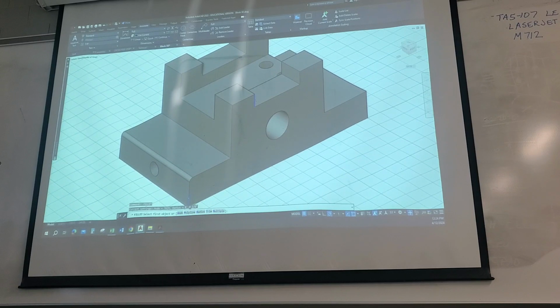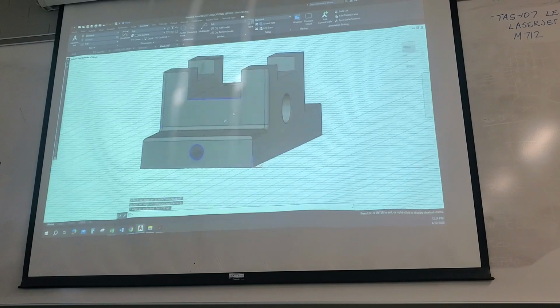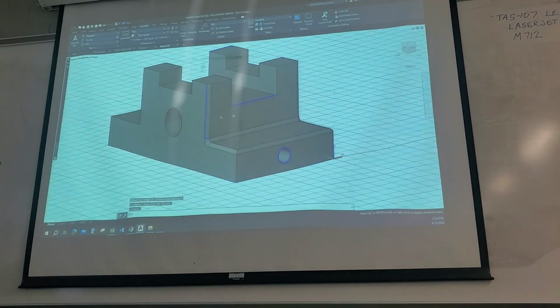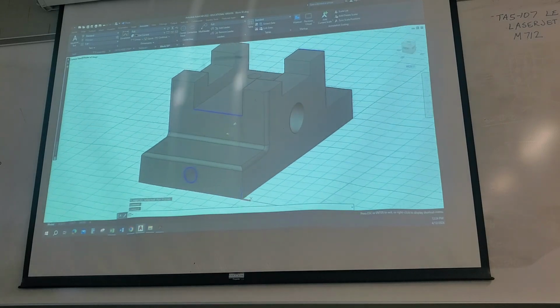On a 3D object, I can go back into it. Once again, I can pick that edge. AutoCAD says, what's the radius? I hit enter or space bar. I haven't used the whole chain feature a lot, but you can. You can select a surface, I believe, and AutoCAD will make it a chain all the way around it. So I picked the horizontal and vertical on these edges, and I also picked this horizontal right here, so I hit space bar. And you can see that AutoCAD put fillets on those corners. Why it's lighting up these other areas in blue, I'm not really sure.